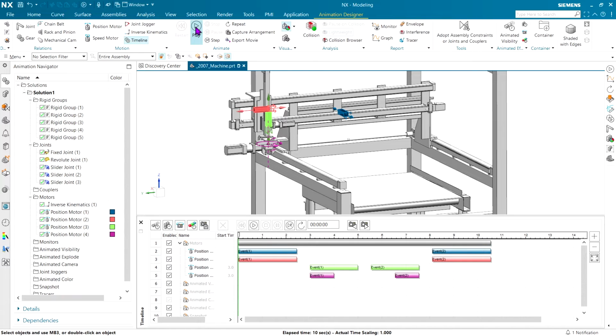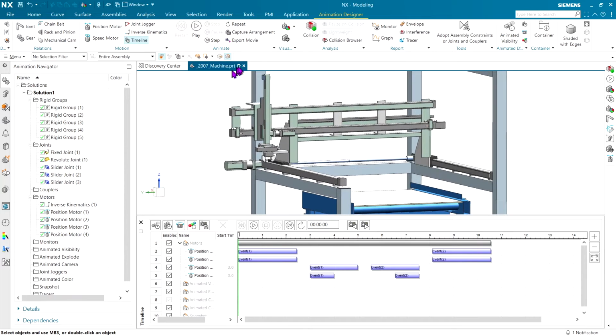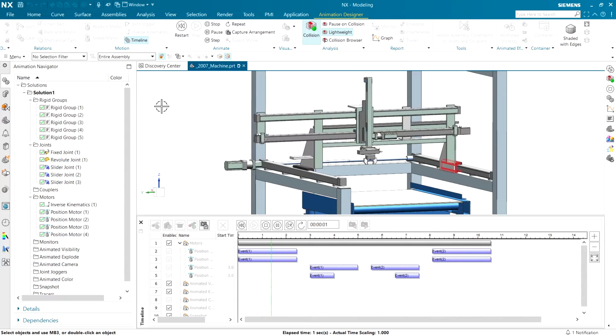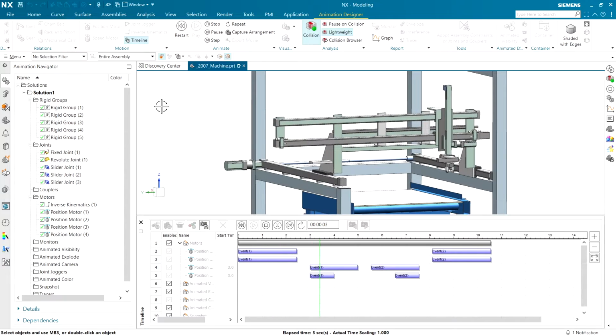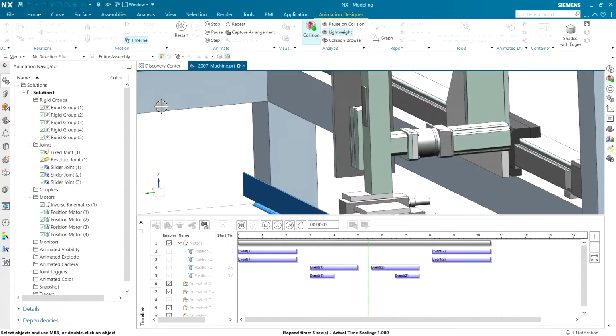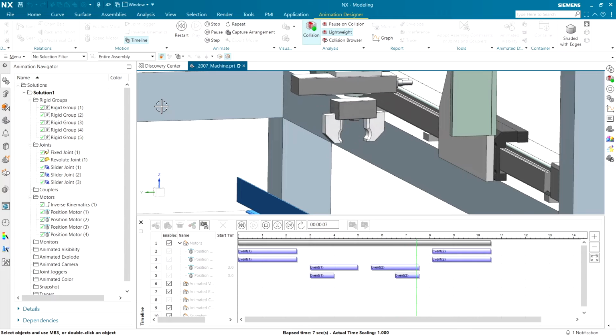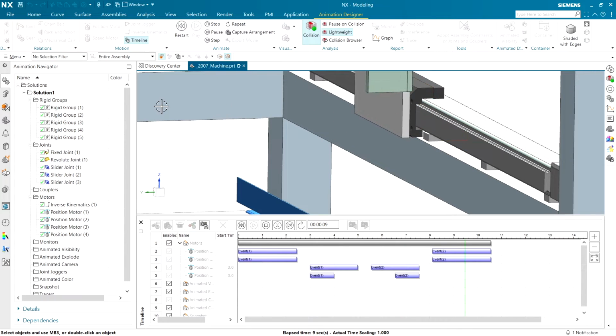The point isn't necessarily making it super correct, but getting a sequence of operations right so we can do, finally, an interference check. So let's turn everything off, and let's turn our collision detection on, and hit the play button and see what happens. And we have a small red collision on the very back of our model. If I zoom in, you can see how it's colliding with something. Don't really know what yet.